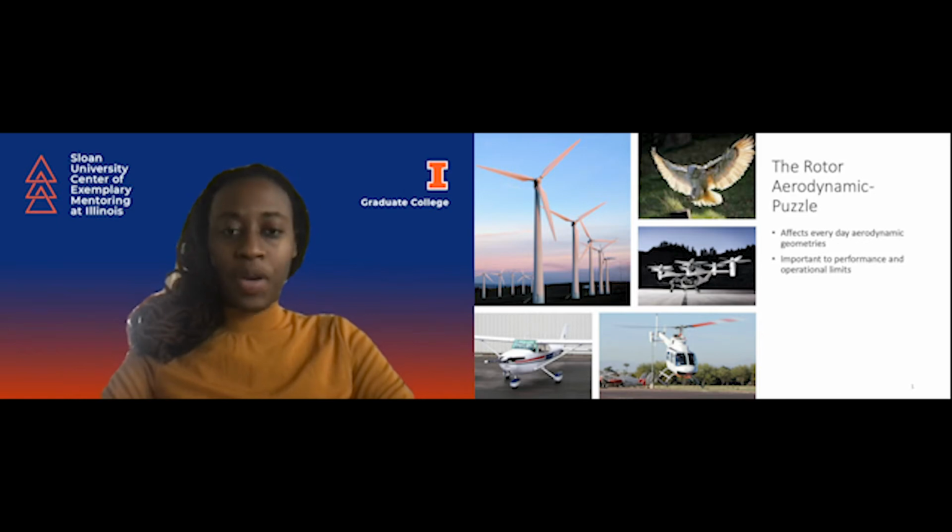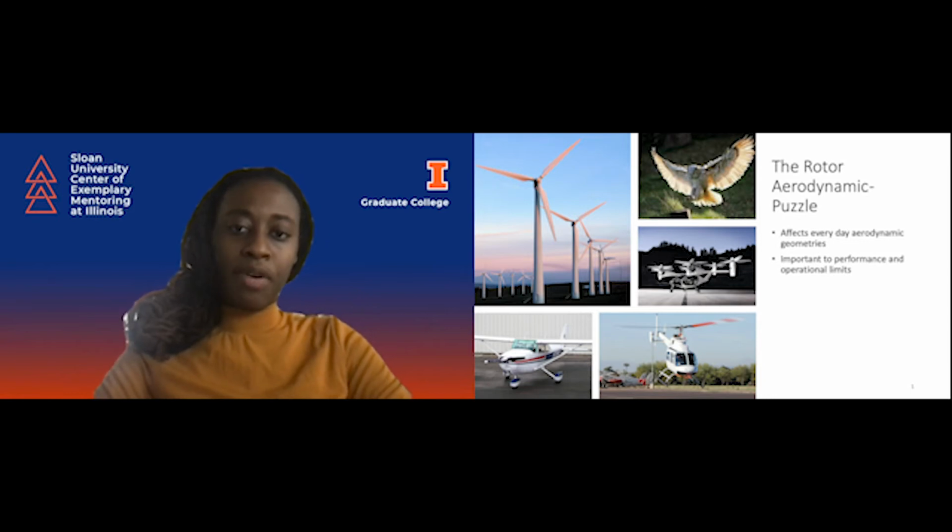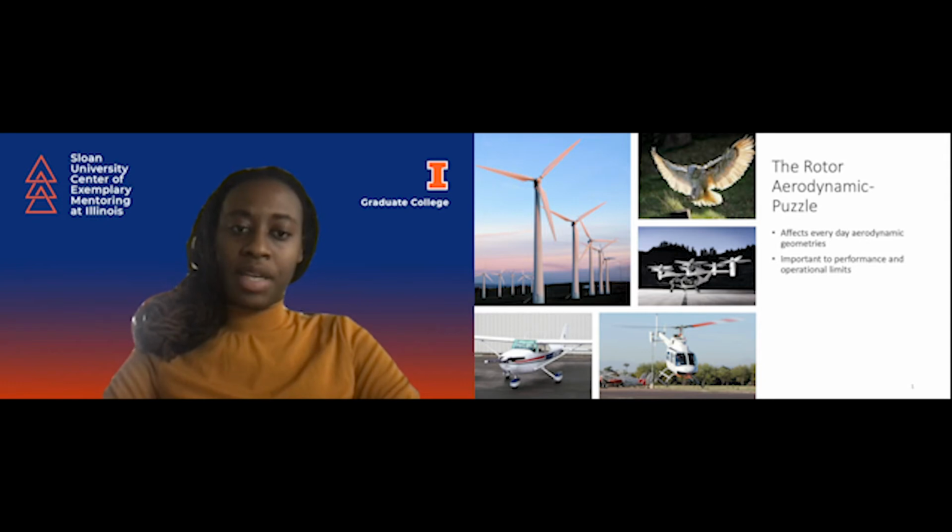I'm sure most of you have spent some time outdoors with nature within the last few months, and perhaps some of you have taken a closer look at birds in flight or landing. If you have, you probably noticed that a bird performed a fast pitch up maneuver during the perching process to keep it from overshooting the branch or telephone wire. In aerodynamics, that action of rapidly pitching a blade or a wing produces a complex phenomenon known as dynamic stall, which results in a highly unsteady flow field around the wing body.